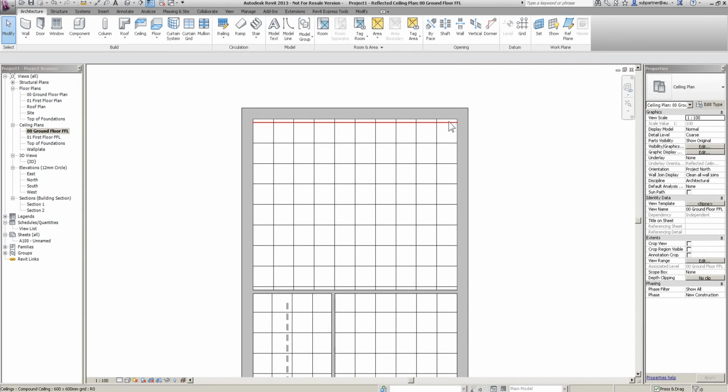For example, in reality, I'm going to move this grid. Now what I'm going to do, I always teach people to create things on their BIM model how you're going to do it in the real world. So in the real world, if you've got a silly little cut across there, your entire grid system would move half a tile. So that's exactly what we do.